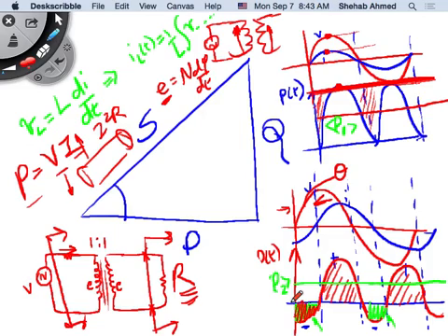The magnetic field in the motor is used to do what? To link the stator and the rotor, so you have two magnetic fields that hold on to each other and they move together, simplistically, right? This magnetic field is set up using reactive power, exactly the same phenomenon. Is it going to affect the amount of average power that you see at the shaft of the motor?